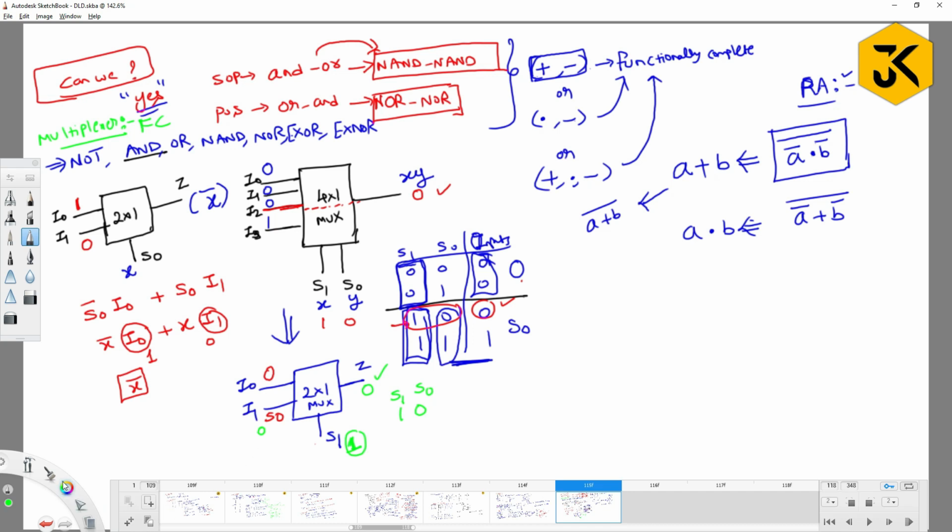Okay. Similarly, I can call this a NOT gate and AND gate. If you take an OR gate, you can do it directly with a 4/1 MUX. What are the inputs for the OR gate? 0, 1, 1, 1, with S1, S0, and this is the output J. This is a 4/1 MUX because I can directly analyze it according to the table.